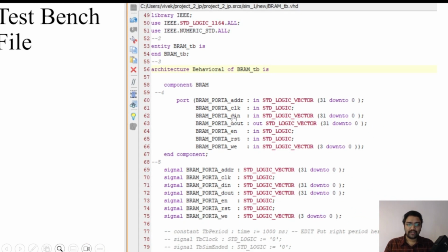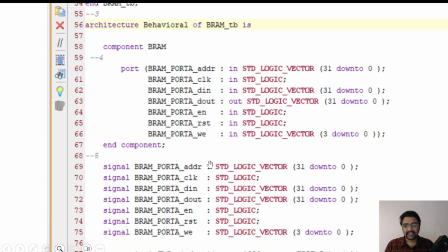So after you declare the ports, go to the signal part, and in the signals, it's block RAM, BRAM port A address and BRAM port A clock. So all these signals, you declare for the ports. For those ports, you need to enable signals. When you say signal, EDA will understand and make the FPGA understand that, okay, this address bus should go through this signal, and enable signal should be there through these ports.